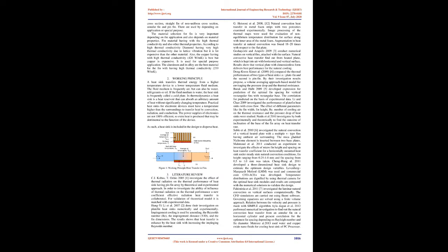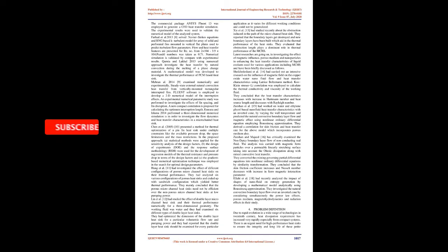3. Conduct numerical studies on vertical fins attached with the surface. Natural convective heat transfer is found from a heated plane kept in air with horizontal and vertical surface. Results show that a vertical plate in dimensionless form delivers the best performance for natural cooling.